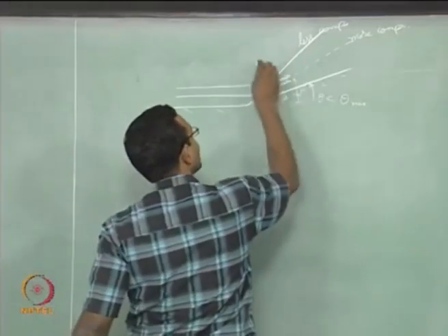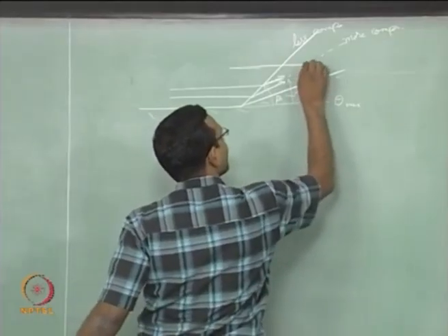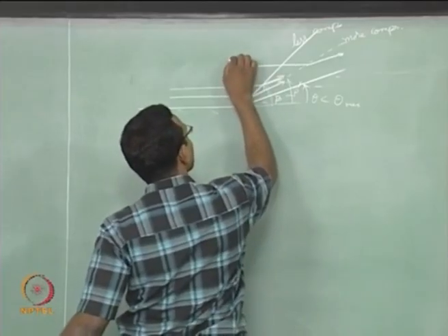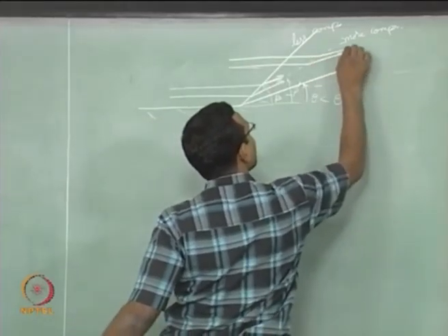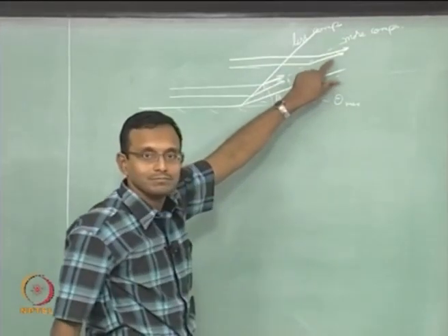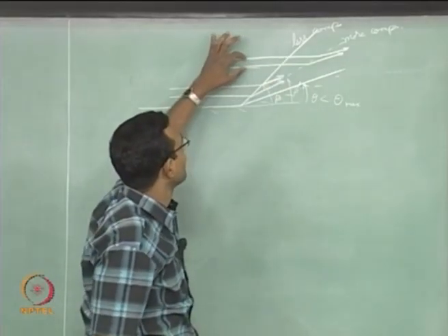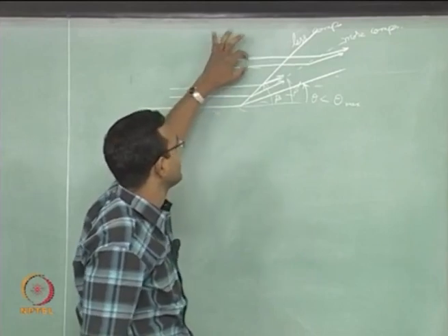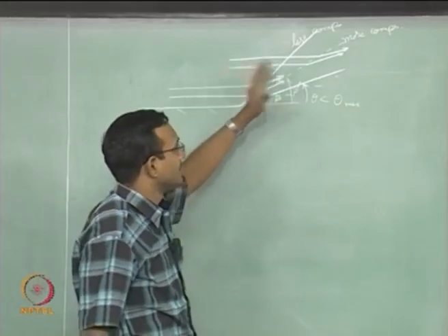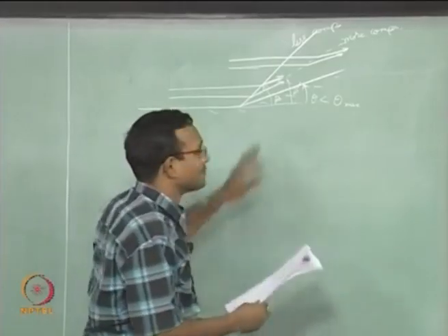If I draw this particular shock streamlines, the other one does not exist for this shock. I will draw the same width at the beginning. Now, you find that from this gap to this gap it is much smaller, that is it is more compressed, the fluid element is more compressed. If it is coming from between these gap, the same width as this, it is much more compressed here than in this case. Okay. That is it is more compressible, so it is getting compressed, easy way to think about it. Okay. This is very simple to explain.